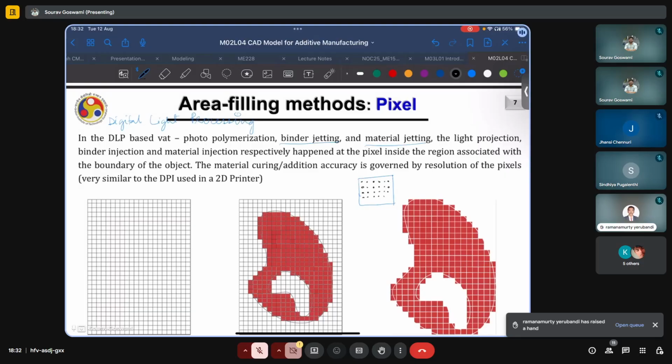And they can be so closely spaced together that we cannot make them apart with naked eyes. And what you will do is in a layer, say if this head is scanning somewhere here, we will only deposit material in these red regions, and for all of these other black regions, the nozzles which are placed here will not be activated.